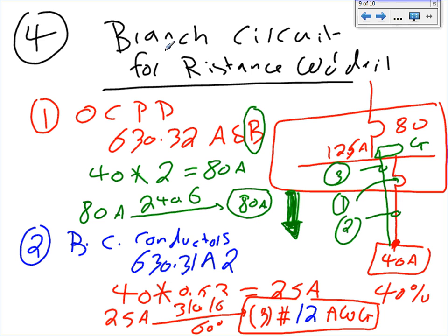I can't emphasize enough, guys, for the branch circuits, to review and go check yourself. And again, Brad, this problem that you just raised is solved in 2011. In 2011, number 12 cannot carry more than 20 amps under the 60-degree column. They solved it. So doing it under 2011, this must be number 10 now.